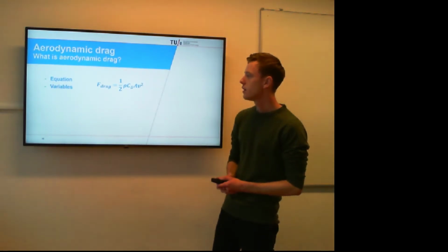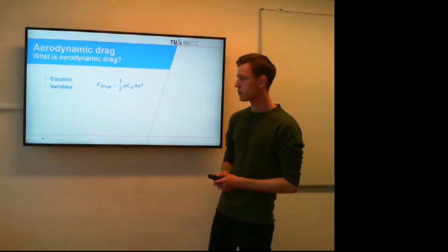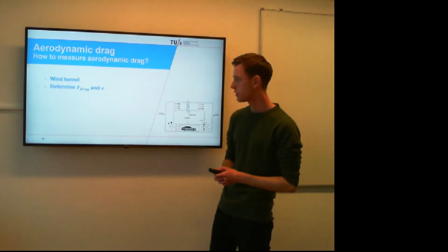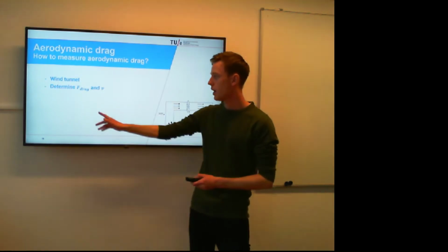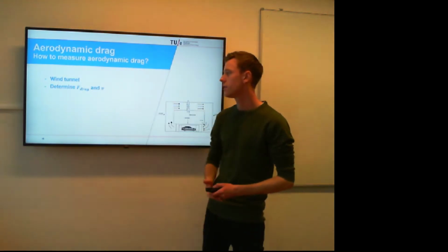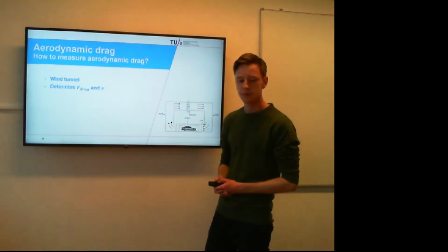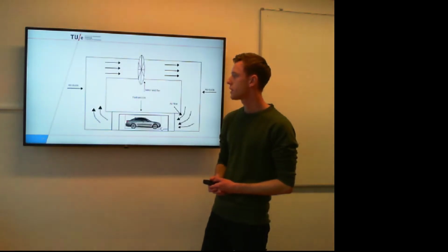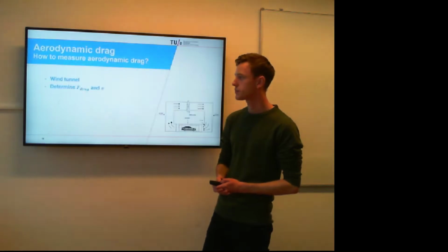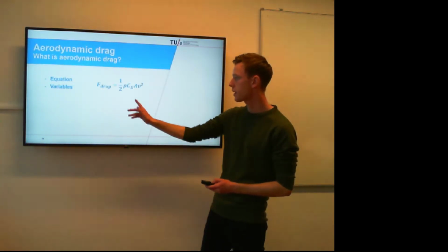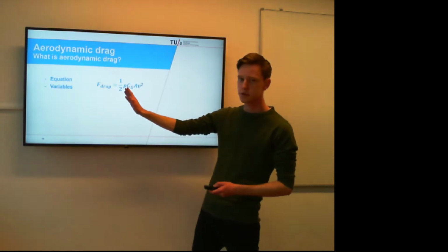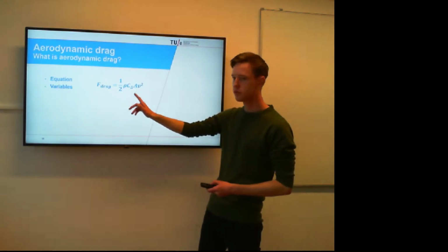And in our wind tunnel that is situated here at the TU/e, we can determine F drag and the velocity of the car, and with that we can calculate the coefficient of drag, because we can also determine the air density and the frontal area of the car.